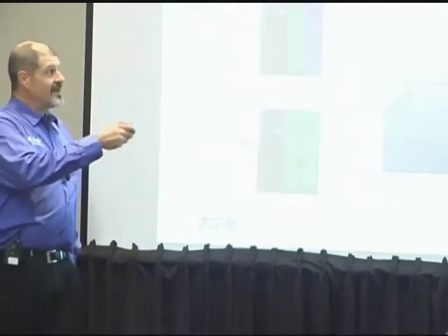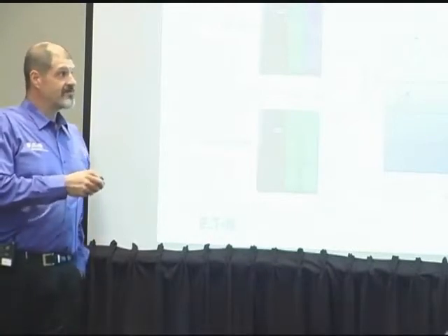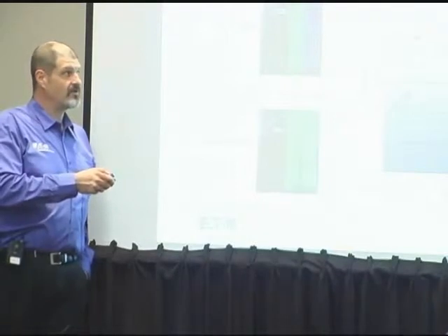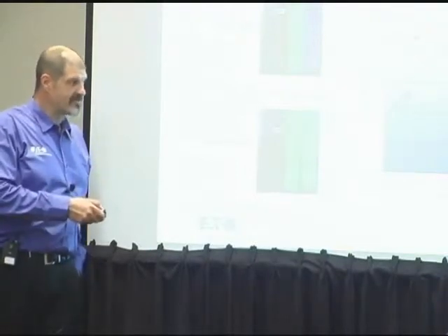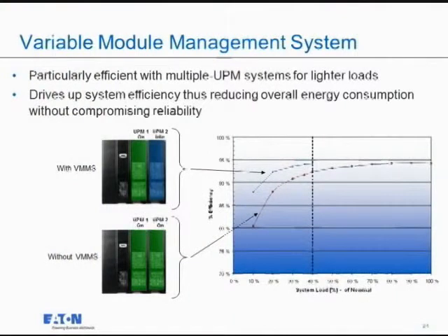By not utilizing one of the modules, this becomes my curve. This is now 275 kVA. This is now full load. This becomes my curve. So I program it so that at 40% load, I simply disable one of the modules. Don't fire it. And again, I'm not turning it off. I'm not opening a breaker. It's still working. It's still synchronizing. It's still ready to go beside it. It's just simply not doing it.